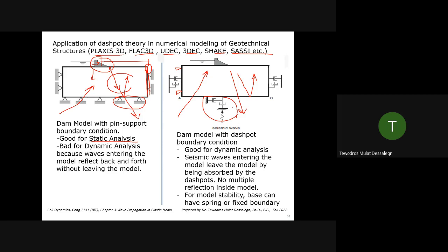What are these dampers, why are we using this damper? These dampers are also, remember the long bar equation. We can take our model to deep inside the earth. But for finite element, finite difference analysis, if you have a large model, you will have a solution error. It takes forever to solve it. But you can cut it down. You can cut it and represent the remaining homogeneous portion just with a damper. All we need is the energy to come out.